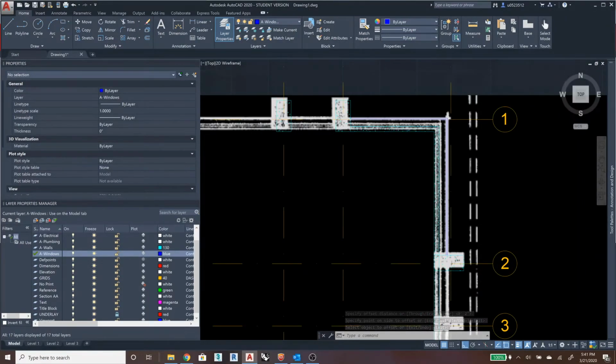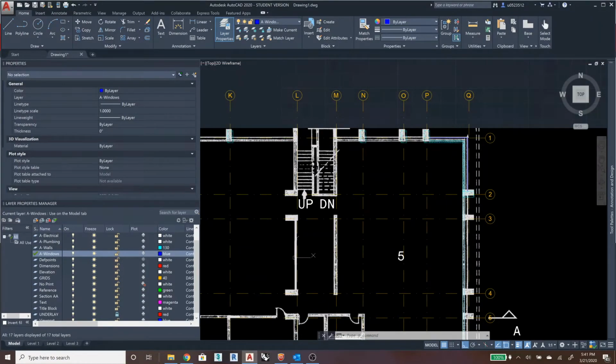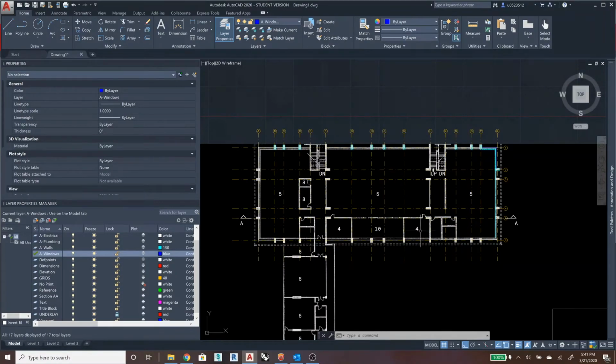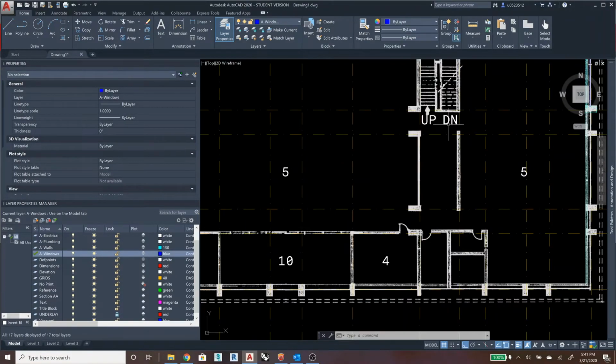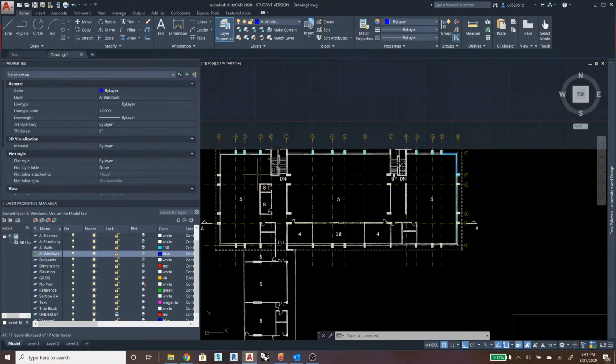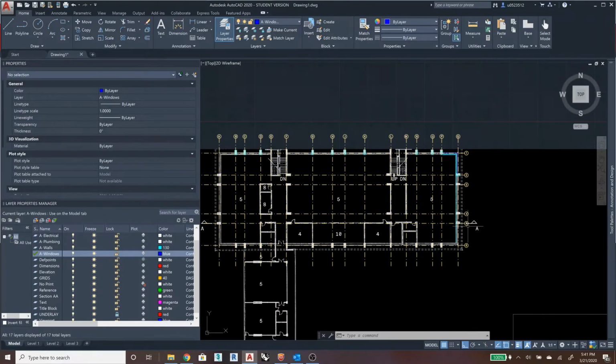I want to just show you what this is going to look like on paper space, and then we can adjust our line weights. You'll want to draw this whole plan that way. So you're going to draw all of these walls, all these columns. Draw everything you see in this region. Don't worry about the stuff down here, just this portion of the building.